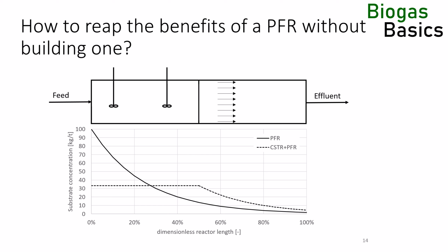So does this mean that a flow reactor will not work in AD? Not necessarily, but the conversion performance will be similar to that of a CSTR, which is cheaper to build and operate than a flow reactor. There is a niche application for flow reactors in AD in thermophilic biowaste fermentation. If the reactor can limit recirculation and axial dispersion, the flow reactor can ensure a guaranteed minimum residence time that is required to pasteurize the biowaste under thermophilic conditions.